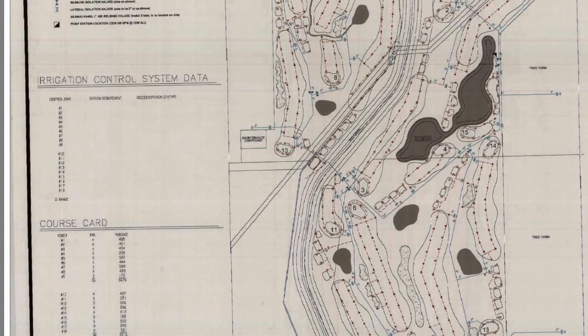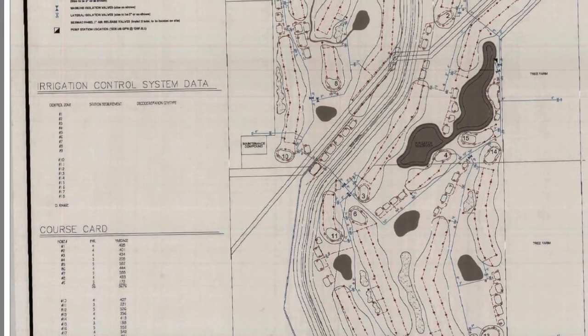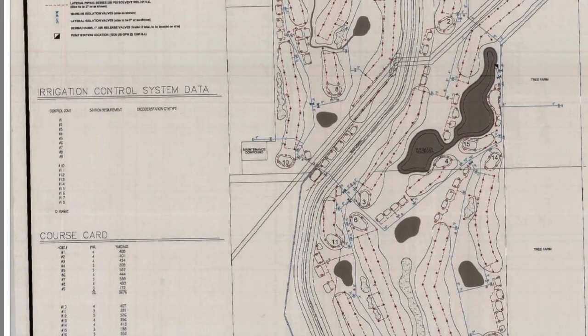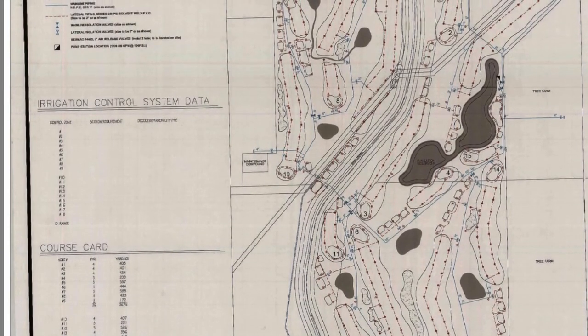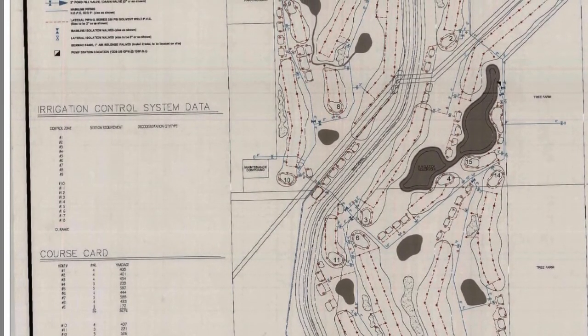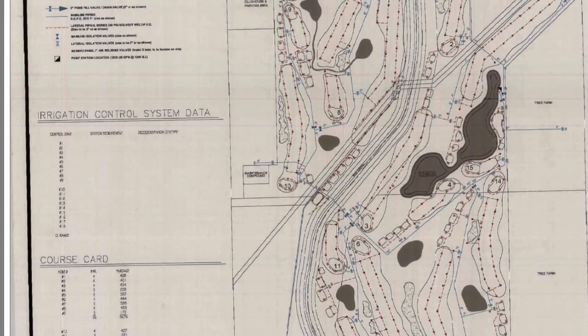For our flow manager to make proper calculations, all branches must be set out in a linear fashion. This is a straight line, because in order for it to calculate the gallons per minute properly, it does not read the loop system properly.